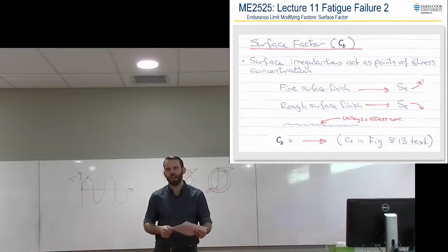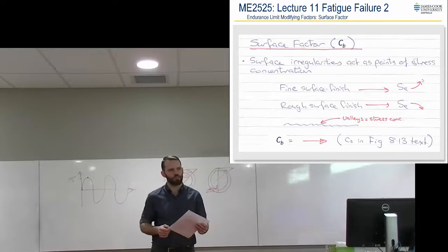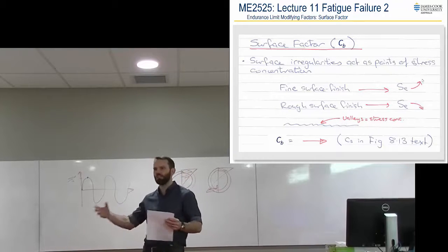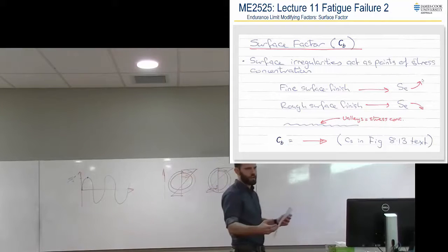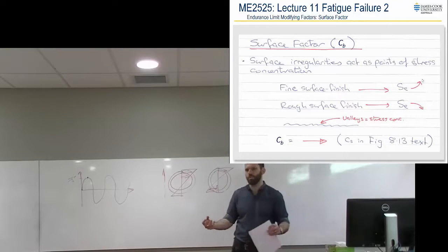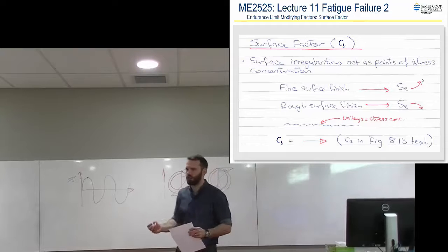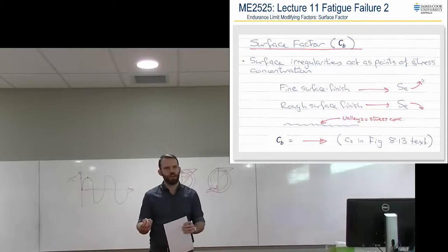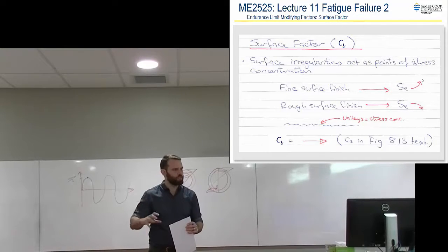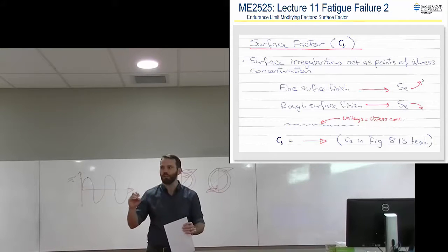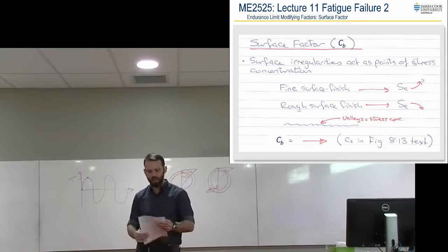So that's about as good a surface finish as you're going to get in a machine shop if you specify that they grind it after they do some sort of milling process. Alright, so just on the mill or the lathe or something like that isn't going to get you this line. This line is then they put it on a proper honing machine or something like that and they actually get a really nice finish. It's not mirror finish, because mirror finish is going to cost you a lot of money. But it's very, very smooth. It's taken any of the burrs away.